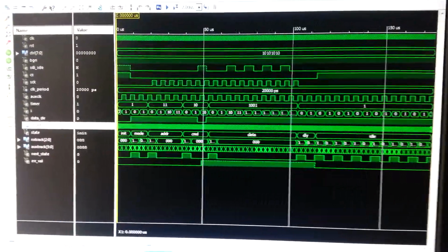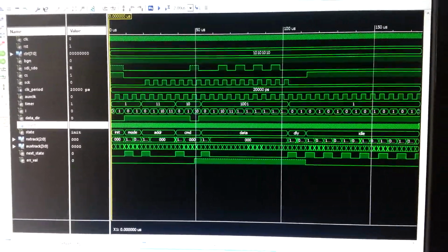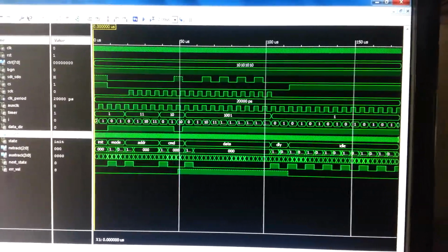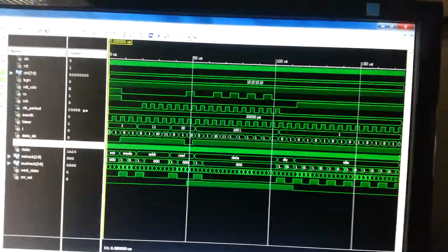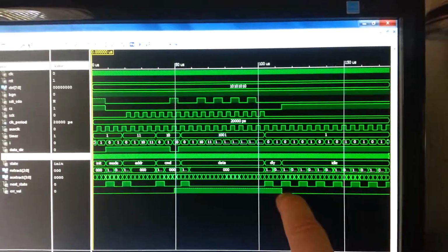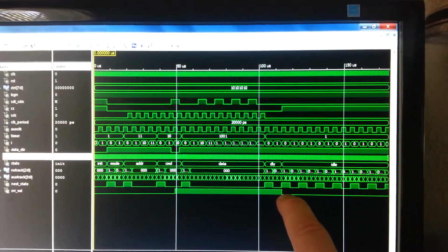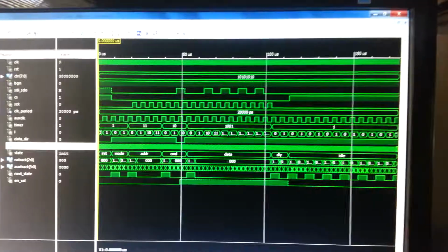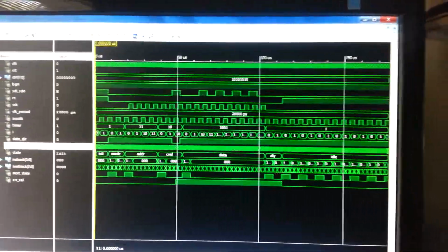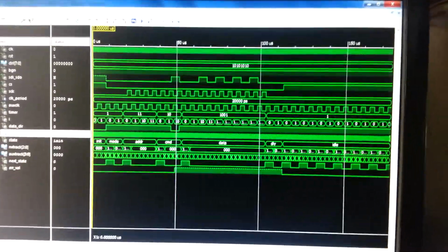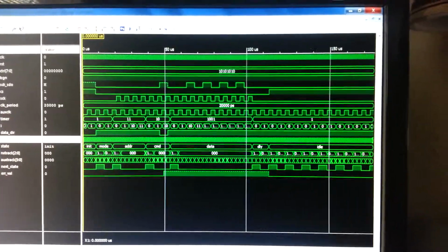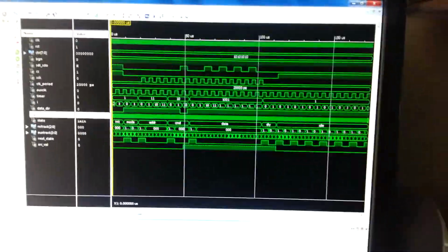The reason I'm doing that is so the simulation can show when the pull-up takes over, and I could monitor when I was capturing that it was giving me something like an acknowledge, but in an SPI case, where it's telling me that it confirmed what I was writing into the device. So I was monitoring that and making sure it was coming up in the right location, and that's why I have it set up that way in the test bench.